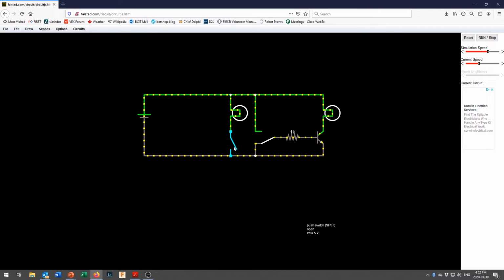Yeah, it's an on-off switch for the motor, but it doesn't provide you the type of logical control that you'd like from your semiconductor devices, from your microcontrollers. So what you can do is you can bring a transistor and put it in line right here. And here I've got an NPN transistor, just a standard NPN. And as you'll recall, with an NPN transistor, electricity flows from the collector through the transistor and out the emitter when there is a small voltage or tiny little bit of current coming in on the base.